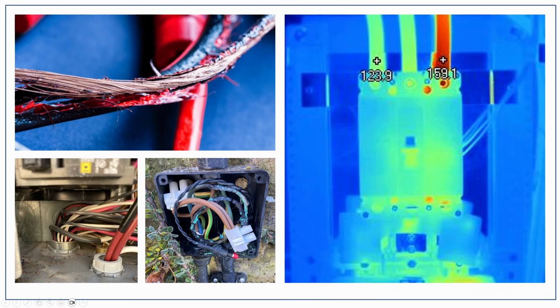And obviously we're going to be costing ourselves money later on, because we're going to have to be troubleshooting and coming back to the installs that have gone crispy because the conductors are pulling too much current and we didn't size the conductors properly.